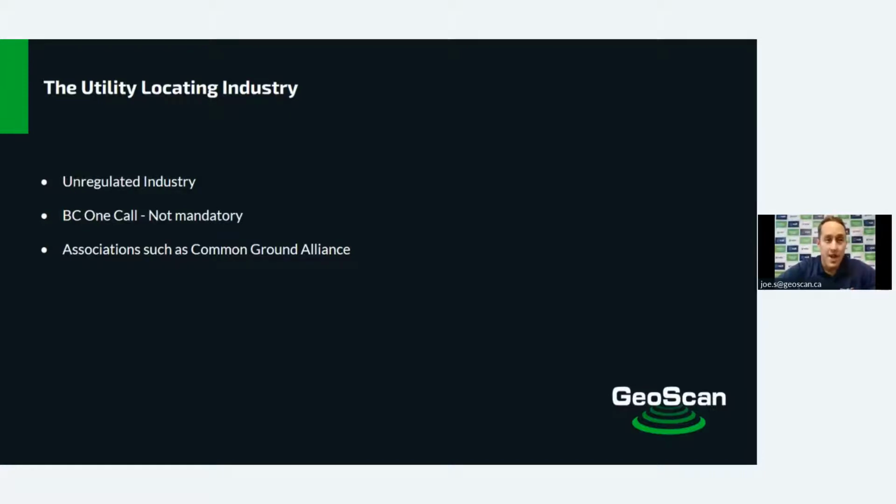Additionally, secondly to they're only as good as the information they have, is that the records are sometimes, often, not correct. So maybe the location of the line that they're reporting on or sending information out won't be georeferenced, might not be accurate. Also, things get changed. Construction happens, modifications happen, and sometimes those records aren't kept up to date. So great service. Always use BC One Call, but also you can't, you know, rely on it solely. You still need to locate utilities on site before breaking ground.